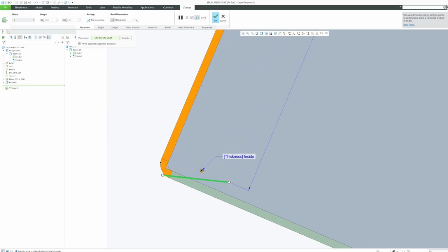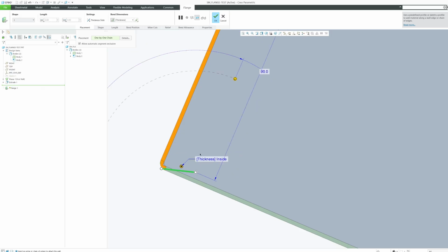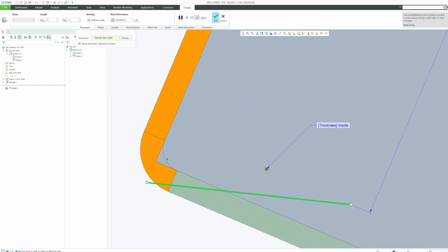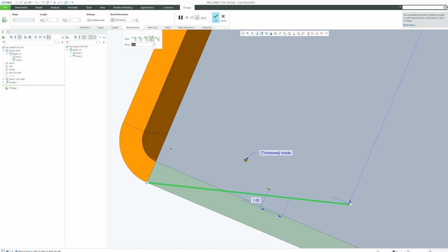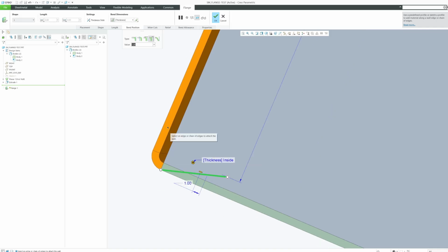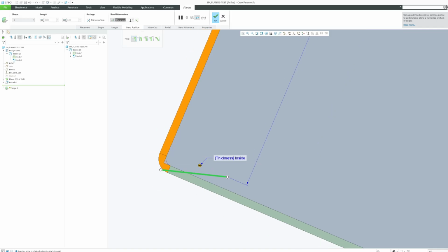Now, you see the flange outside the box, but the bending radius is still biting into the inner volume. To avoid this, we can offset the flange to bend away from the edge by a certain amount, not more than the inner radius. Or reduce the radius of bend. This is purely dependent on the manufacturing feasibility.